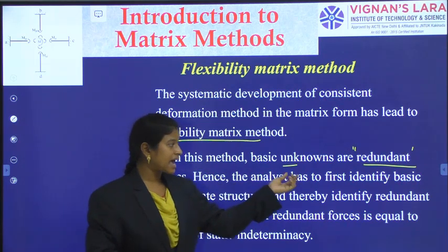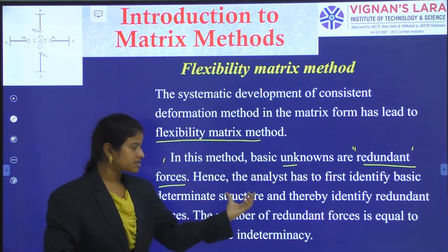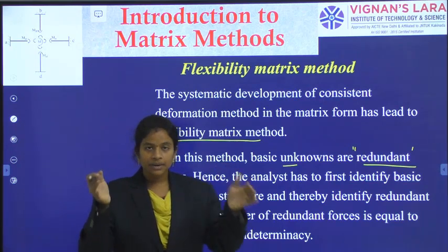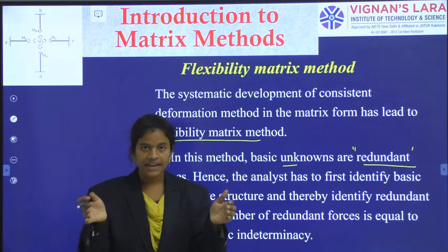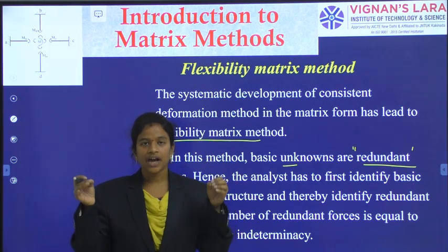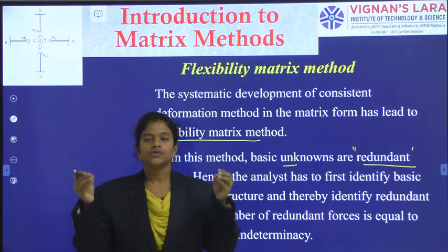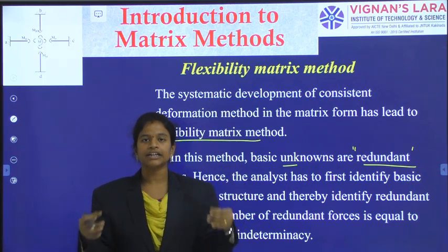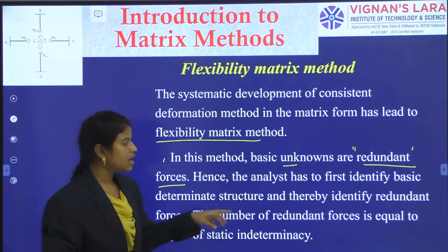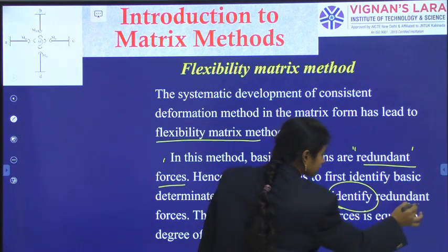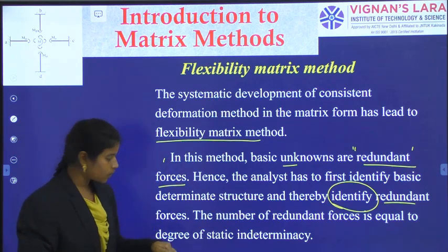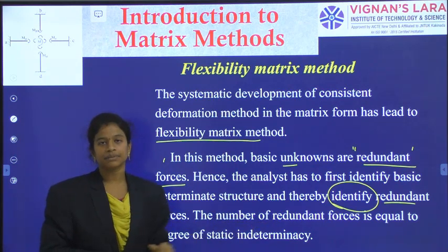Hence, the analyst has to identify the basic determinate structure and thereby identify the redundant forces. So, from the indeterminate structure, I have to identify a determinate structure. So that while I am doing the determinate and indeterminate conversion, I can observe what the redundant forces are. Okay, so I have to identify those redundant forces. Okay, the number of redundant forces is equal to the degree of static indeterminacy.